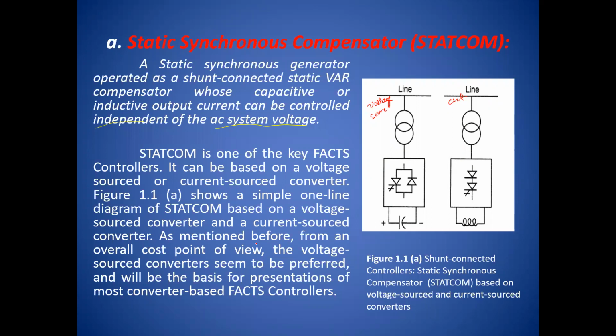So this is the static synchronous generator operated as a shunt connected synchronous VAR compensator whose capacitive or inductive output current can be controlled. Definitely the current should be in phase quadrature with the voltage, and it is either going to inject capacitive current or absorb inductive current.